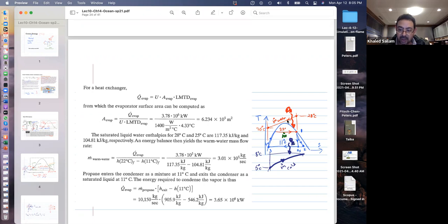The Q dot that's going to the warm water is m dot delta H, which you can do two ways. You can do it m dot Cp delta T, right? Or you can do it from the steam table. So that warm water, if you give the steam table its temperature and you treat it as compressed liquid, what's a compressed liquid? It's this part. I'm not referring to propane. I'm referring, if this was a TS diagram of water, the compressed liquid part would be this side, right? And so what they usually do is that if you say I have 22, it doesn't matter how high the pressure is, they just give you the H saturated. So they think the H is only a function of temperature, not of pressure. And that's a good approximation, right?